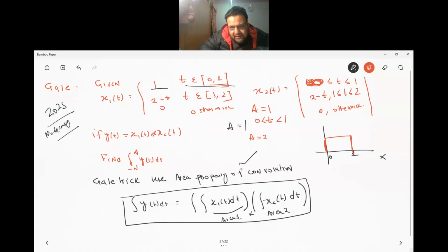The amplitude of the signal is equal to 2 minus t when time lies between 1 to 2, right? So 1 to 2 is this process. When you put t equal to 1, the amplitude becomes 1, that is good. But if you put the endpoint t equal to 2, what happens to the amplitude? 2 minus 2, 0. That is only possible if it goes like this, because at 2 it is like this, at 1 it is like this.